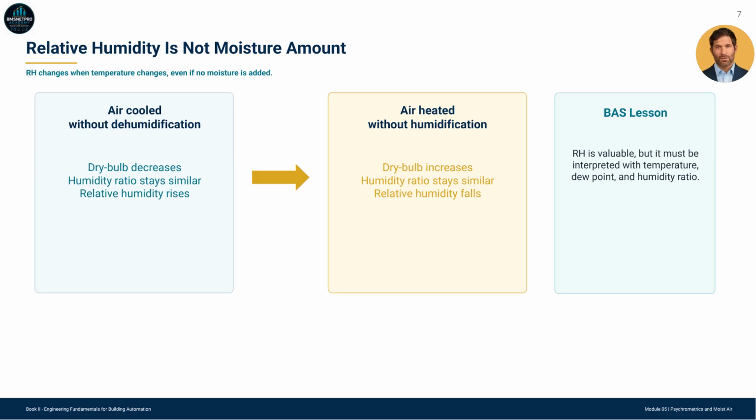This is why we interpret relative humidity together with dry bulb temperature, dew point, and when needed, humidity ratio. RH alone is not enough evidence for a professional decision.